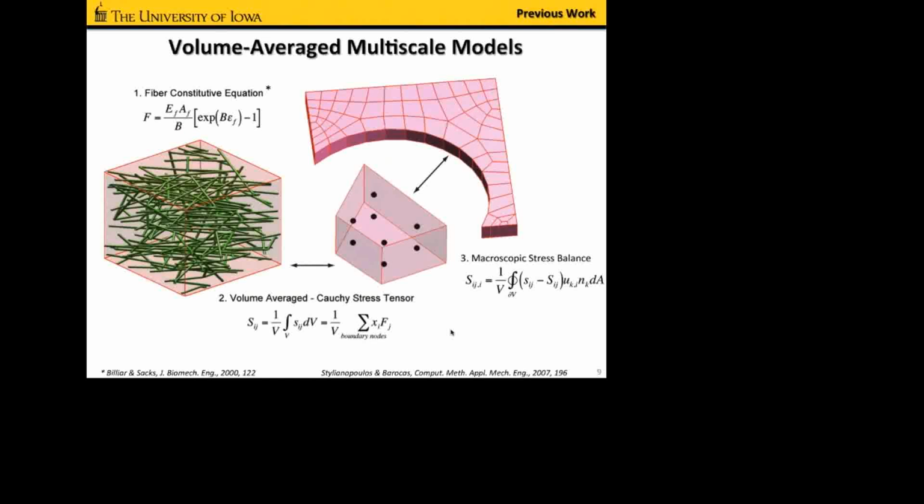We have a computational modeling framework that's been developed over several years. We use volume averaging in concert with finite element simulations. Here you can see a finite element domain that represents one quadrant of a cruciform, assuming symmetry. What's different here is that instead of using a constitutive equation at the continuum level to relate displacements to the stress, we solve a set of microscopic fiber network problems at the location where the stress is needed to get the finite element solution.